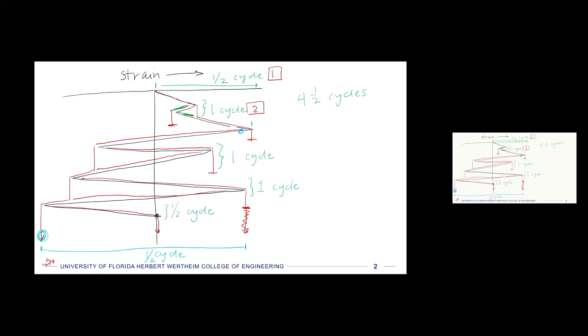And then as we kept going down, we had that big half cycle, our next rainflow down. So the third one is actually that longest one that I wrote on the bottom. Then we keep going down in time. Then we have this one, the intermittent one, then the other intermittent one, and then finally this half cycle. So each of those phases has its own amplitude and mean, and you can see now that this is why we need automated modeling methods to account for this.